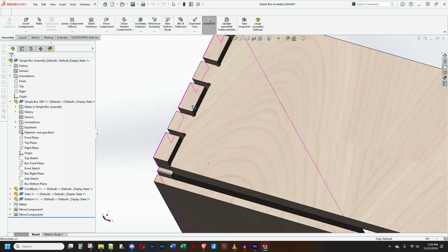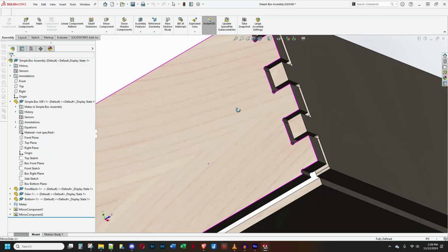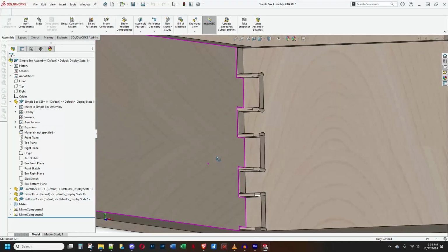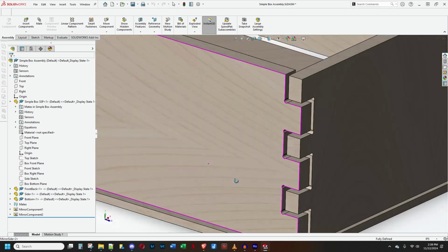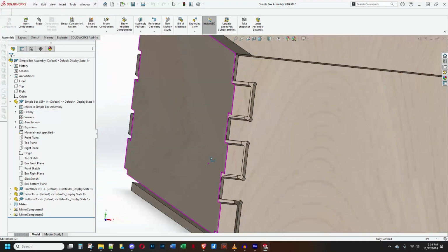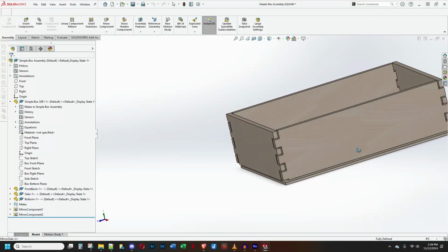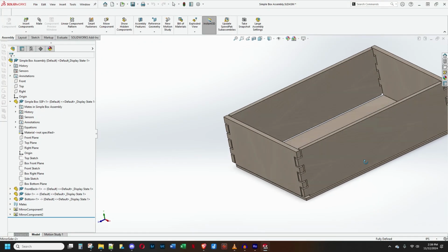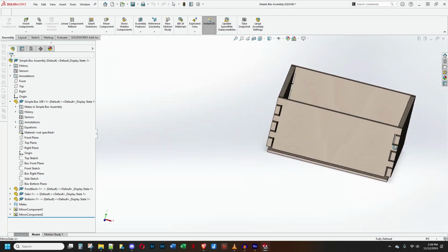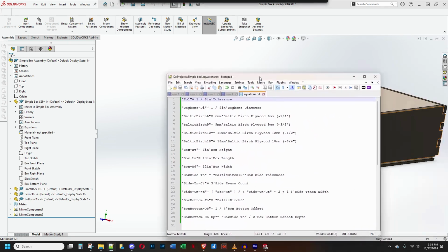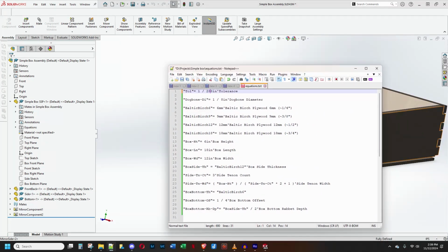But you can see at the bottom, I've got the tolerance so wide that the bottom gap has kind of disappeared from the board, but that's okay. The main thing is I'm checking to see that the tolerance is evenly applied all the way around the joint. And I know if I've got one corner, I'm pretty much assured, because of the way I've done things with repeating sketch patterns and mirrors, that I've got it all the way around. I don't need to over-examine. But that's one quick way to test your tolerances. So I'll put it back. Oh, 128. There we go.